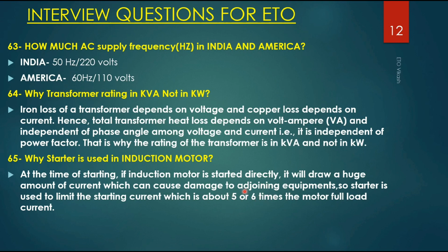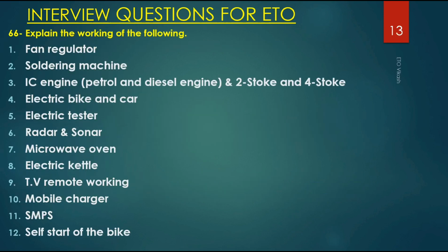So heating goes as the square of the current, and because of that the cable and the winding of the motor will burn. So in the starter we reduce the voltage so that the starting current is reduced, and when the motor starts running we give the full voltage.